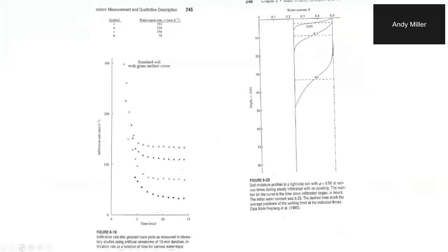So what they're saying here is that it has no ponding, which means that, so this is water content. It's between about 23% and about 50%, and if you got 50%, you're probably saturated in most soils. So this might be saturation at the surface, but yet it's not so saturated that it can't have water infiltrate. There's no ponding.